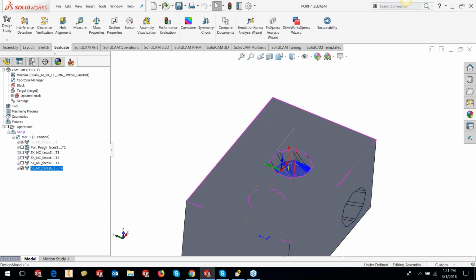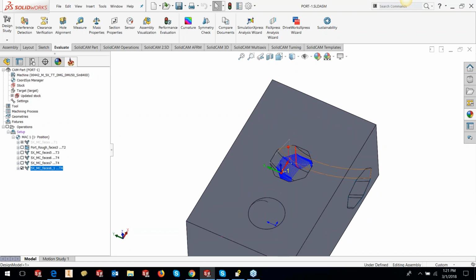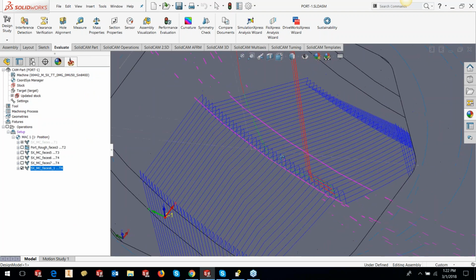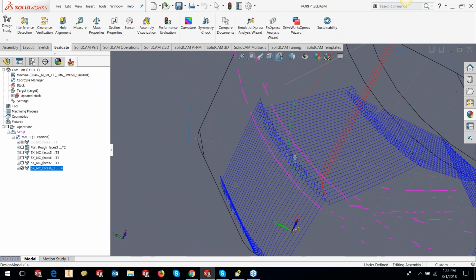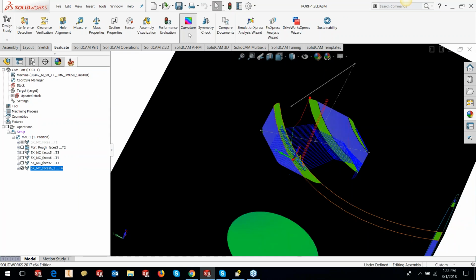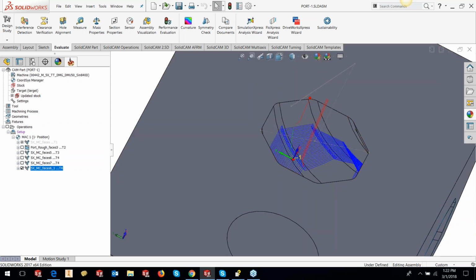Okay, so I have basically the tool path, and you can see that very soon it's a mess. Okay, it doesn't look good in any sense. Why? Mainly because the curvature here is smaller than the tool curvature or the tool radius. Okay, this is R12 and I'm using an R16 tool.